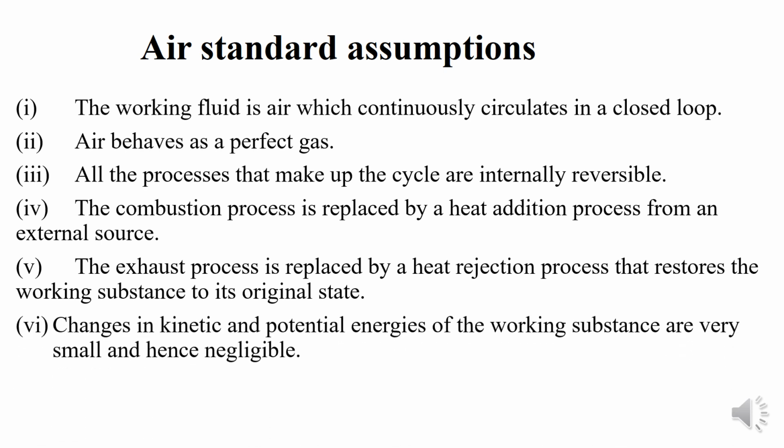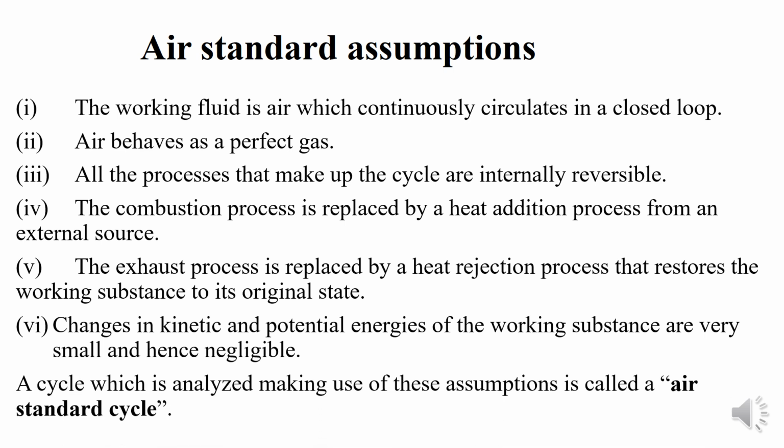Next, changes in the kinetic energy and potential energy of the working substance are negligible, and we are not considering them, because only heat energy, or temperature and pressure energy, is there in the working fluid. Compared to that energy, kinetic and potential energy are very small, so they are neglected while deriving equations. These are the assumptions we make in the air standard cycle, and this cycle is known as the air standard cycle.